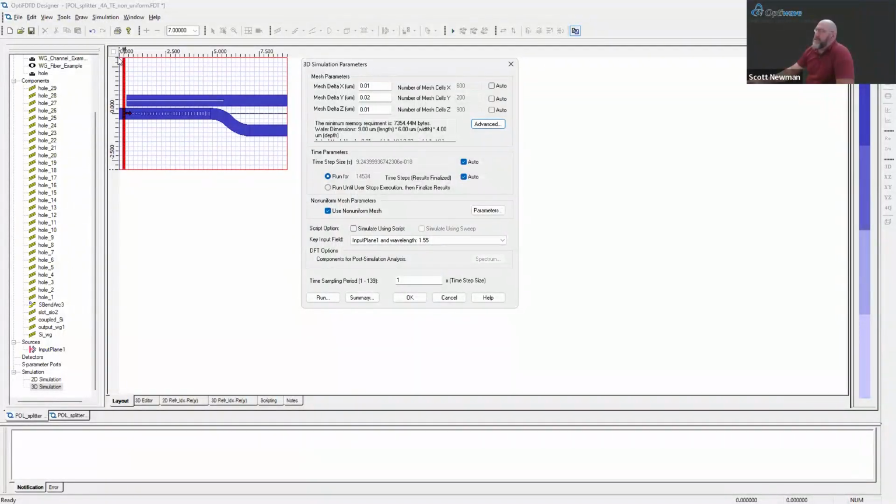What the auto does is it takes a look at the longest distance that the light could travel, from opposing corners, and how long it would take to travel that distance in the highest index material. This is fine for any structure without resonance or with a low Q. But as soon as you start getting into resonators, Fabry-Perot cavities, anything that can have any reasonable Q factor, you will find the light bouncing back and forth within that resonant structure is going to need more time to propagate through and get to whatever your output is.